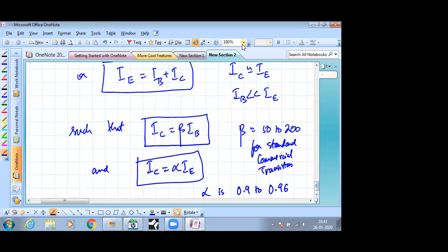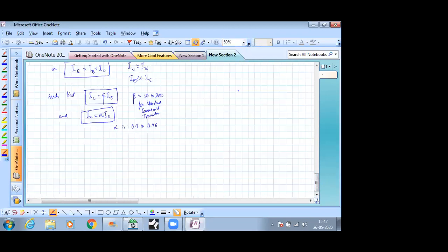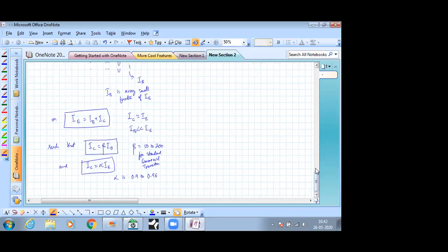Okay. So these alpha beta parameters are actually nothing but a function of the design of the transistor. That is, what kind of materials are used for the individual base, emitter, collector, what kind of concentration they have for the dopant, and also what values of voltage we are using for the biasing. So any commercial transistor will come with a rated value of alpha and beta, such that if you connect to the correct DC voltages which the transistor has been designed for, then it immediately achieves these ratios which are given by alpha and beta.